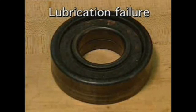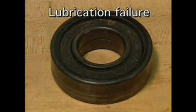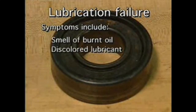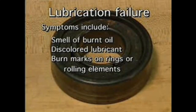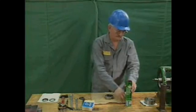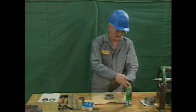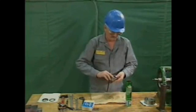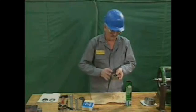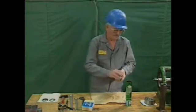Another type of bearing failure is lubrication failure. Lubrication failure occurs when the oil or grease in a bearing fails to function correctly and the bearing overheats. Symptoms of lubrication failure include the smell of burnt oil, discolored lubricant, and burn marks on the rings or rolling elements. Lubrication failure can also be caused by improper lubrication. This could mean too much or too little lubricant, using the wrong kind of lubricant, mixing lubricants that aren't compatible, or using contaminated lubricant.